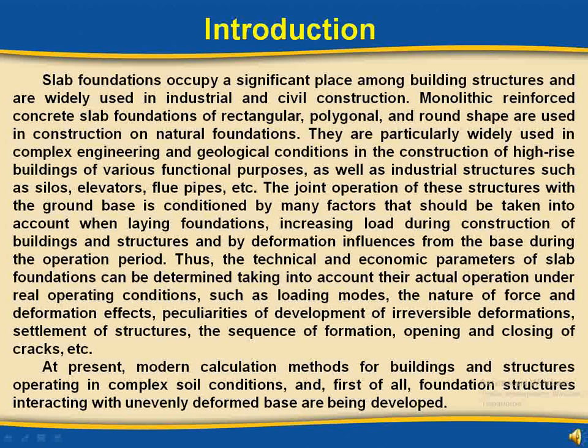Slab foundations occupy a significant place among building structures and are widely used in industrial and civil construction. Monolithic reinforced concrete slab foundations of rectangular, polygonal, and round shape are used in construction on natural foundations. They are particularly widely used in complex engineering and geological conditions in the construction of high-rise buildings of various functional purposes, as well as industrial structures such as silos, elevators, flue pipes, etc.